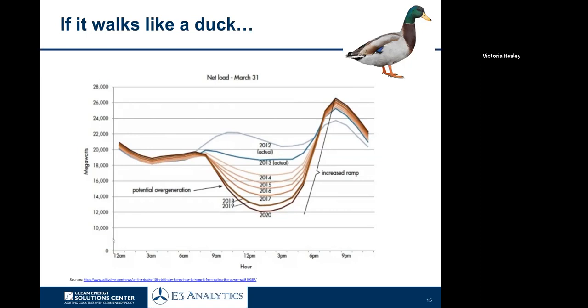And then you can see essentially this graph is showing the net load. In other words, the load after solar. So this is sometimes what's referred to as the residual load to be met. So the utility needs to basically meet actual power demand. But when a growing amount of that is being supplied by solar PV, which is being fed into the network and accepted typically on a priority basis, it shifts the net load downwards.